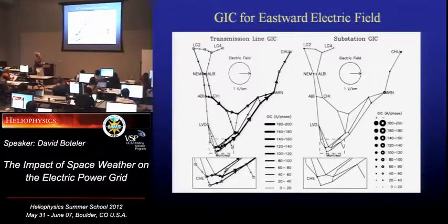What they've done to improve the AC flow is put bigger capacitors in these lines. But that has the added effect that it blocks the GIC. But it's only in the north-south lines. It's not in these little interconnecting lines. So we're going to be examining just how much GIC flows in these and how much of an effect there is on the system, because Hydro-Quebec is still seeing harmonics on their system during magnetic storms. If it was all just north-south, you wouldn't see anything. So there's still some GIC flowing somewhere, and we're going to try and pin down exactly where it's going.